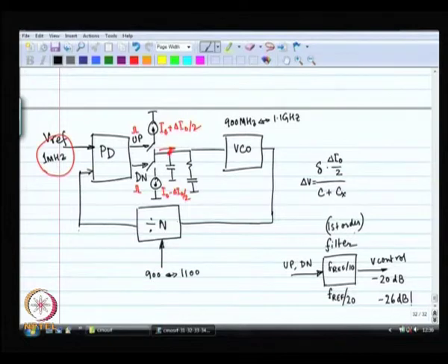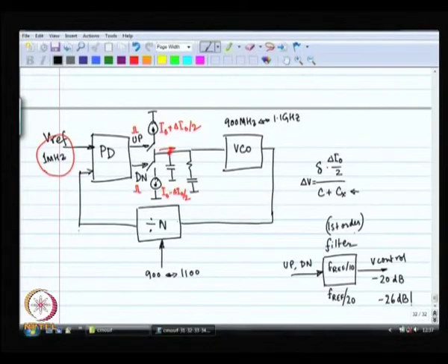Right. So, what I am suggesting over here, is that consistent? If I halve the bandwidth, that means I am doubling the capacitance. If I double the capacitance, then the size of these delta V's becomes half. So, it is the same phenomenon. So, it agrees.